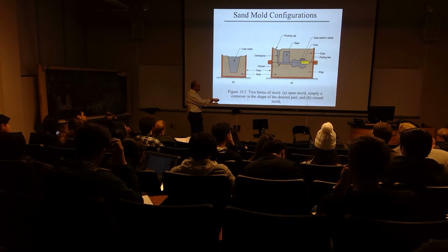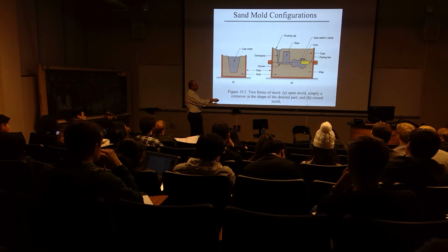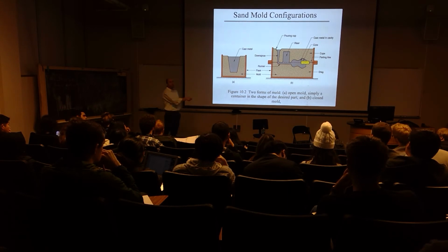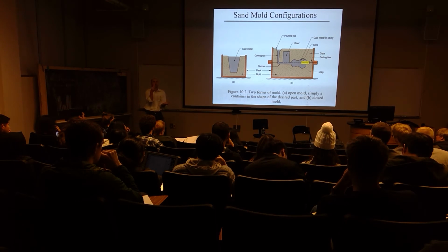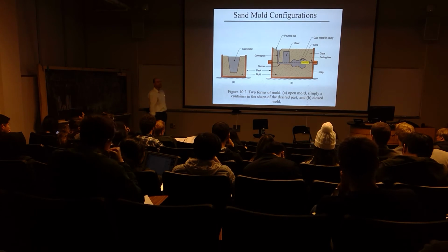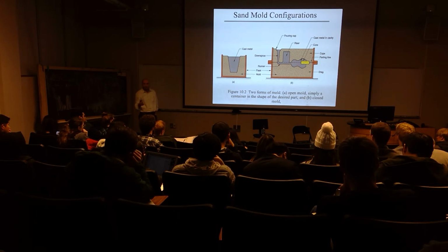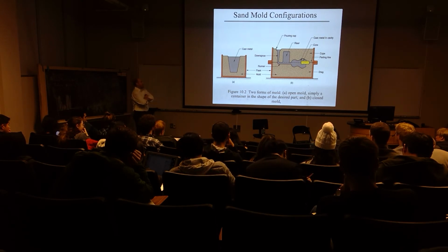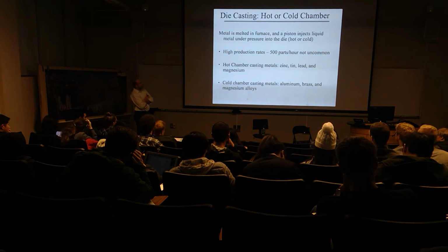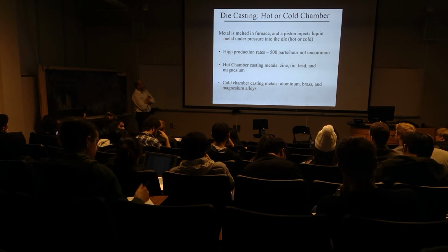And we always think about the parting line that's present in these particular components, because the parting line references the line of, not necessarily symmetry, but the line of division between the cope and the drag of that mold that's used to develop the part. Okay? I'll bring parts with me next time so that we'll talk about that and the importance of that in failure analysis shortly.